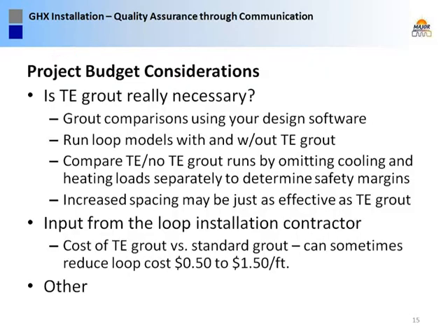Okay, budget considerations. One of the things we see a lot, and you can talk to your driller about this, again, this goes back to communications, is some drillers charge a premium for thermally enhanced grout, others not so much. What we found in the markets that we design in, that if you're going to go to a 0.90 thermal conductivity grout or even higher at 1.10, you're going to add anywhere from 50 cents to $1.50 per foot to the installed cost.